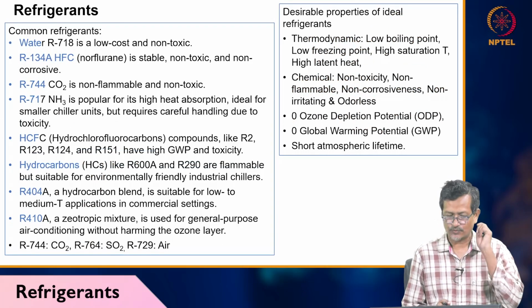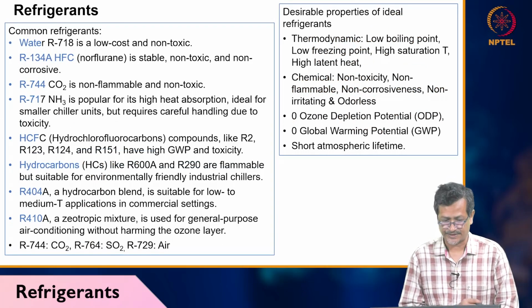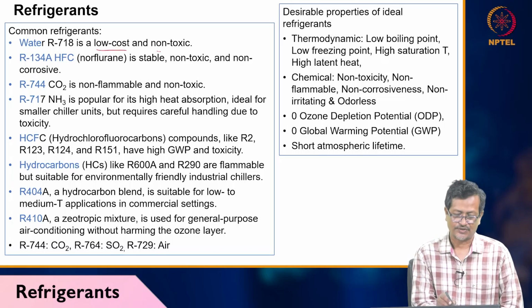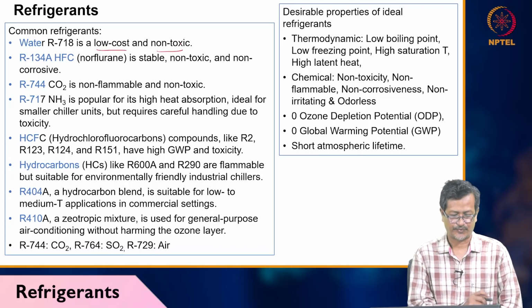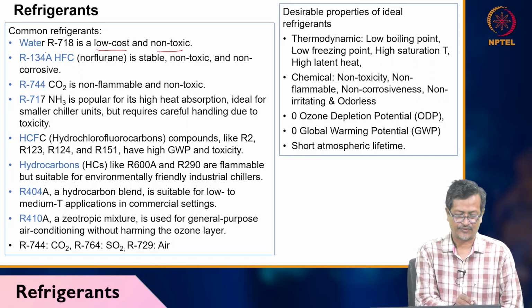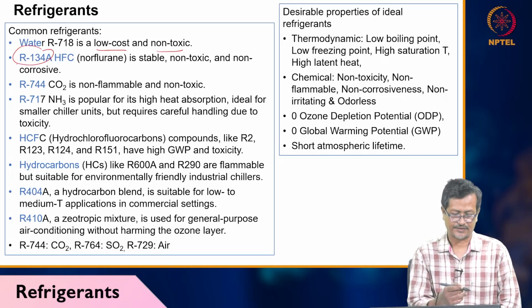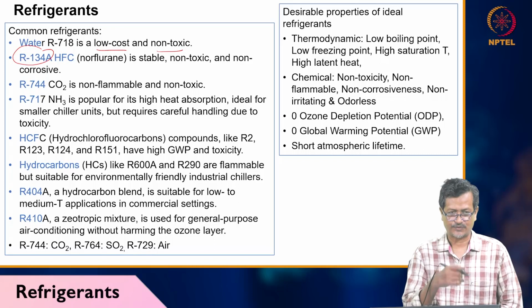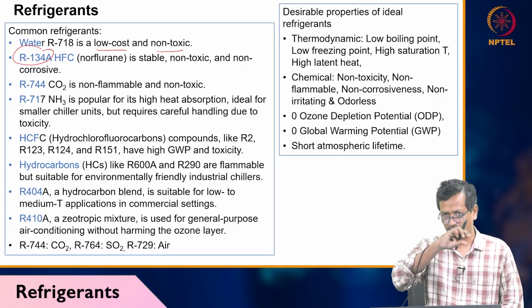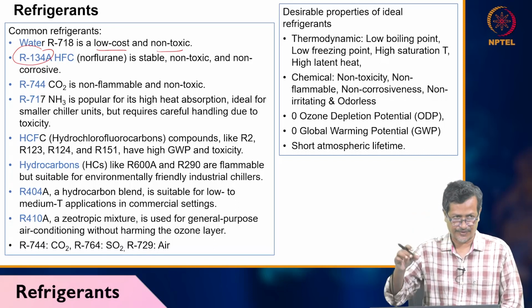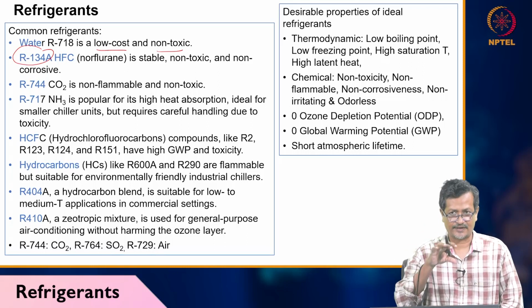Common refrigerant, for example, water can also be one refrigerant. It is low cost and non-toxic, so it is very popular in many cases. R134A is also a very popular refrigerant. So these are called refrigerants. A refrigerant is a working fluid flowing through the compressor, condenser, and evaporator. That fluid is called refrigerant.